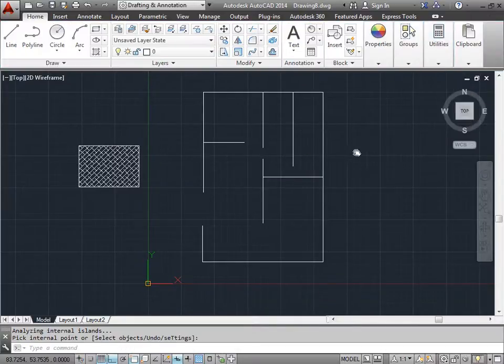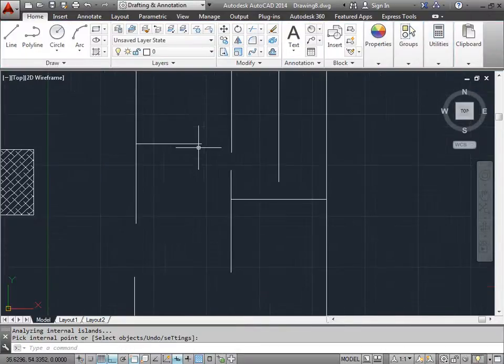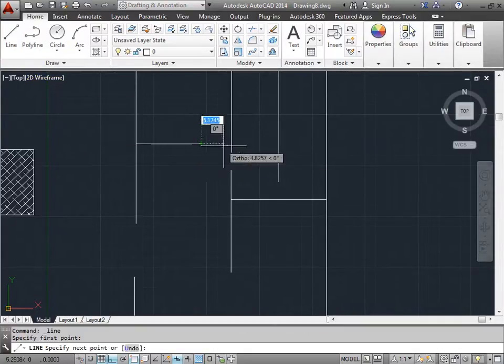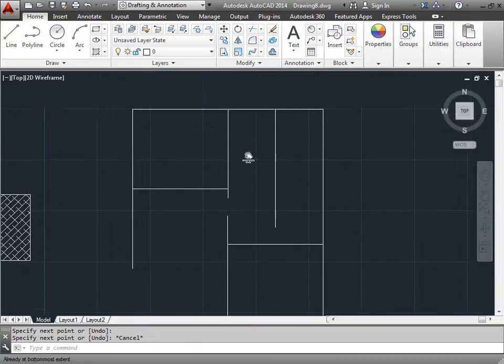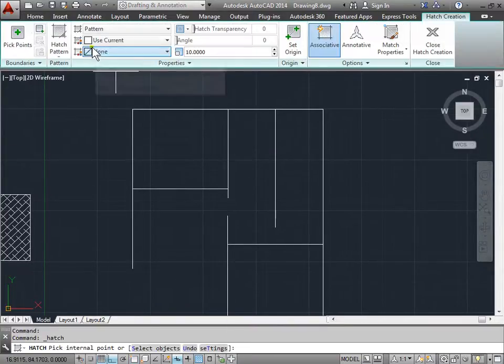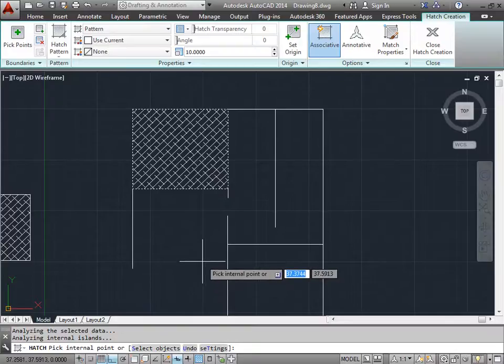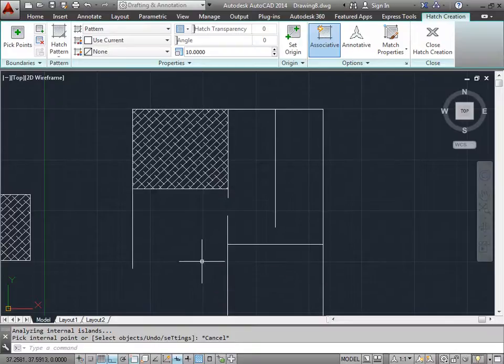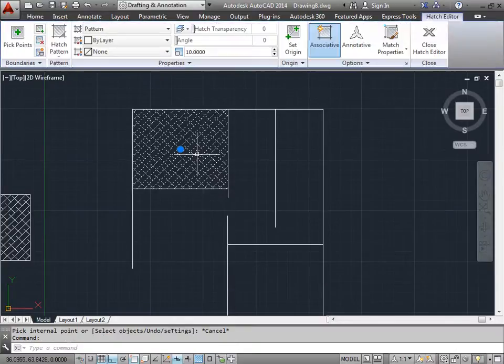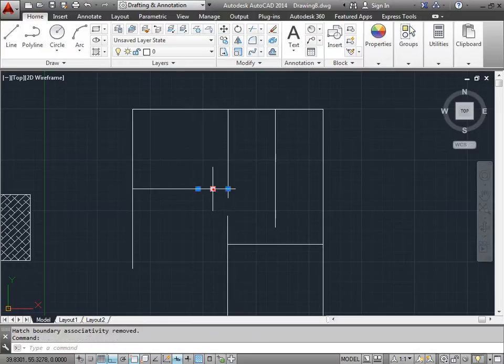One thing we can do is, I'll pan over to the side, zoom in, we can add a line from this point to this point here, deselect, and then continue hatching the area like normal. But that can sometimes be inconvenient. Let's see what else we can do. I'll go ahead and delete that, select this line, and delete that as well.